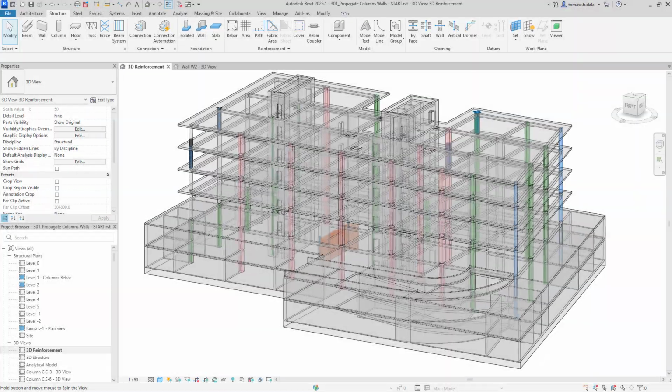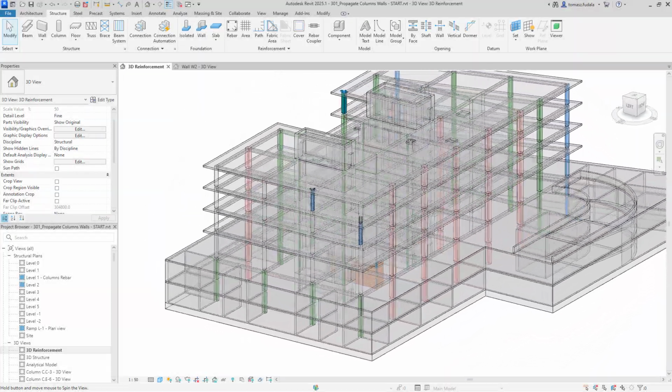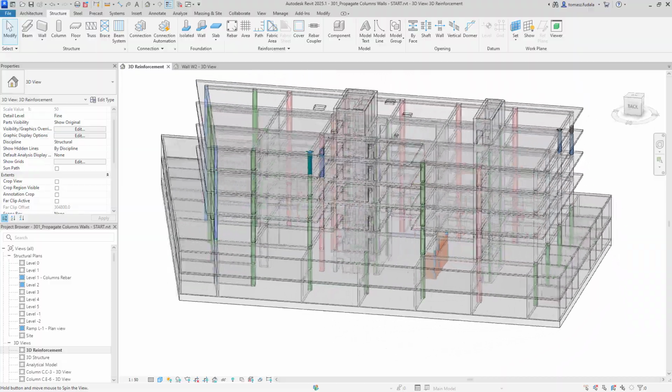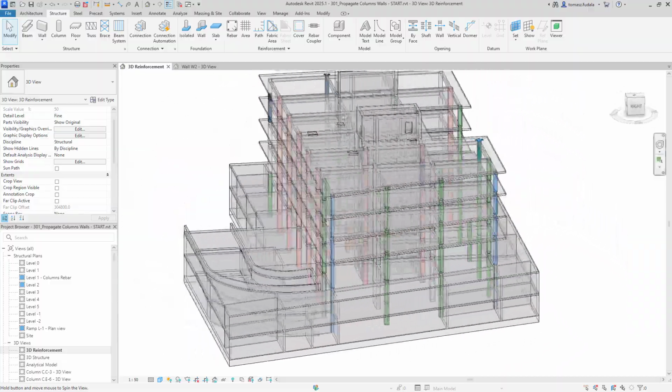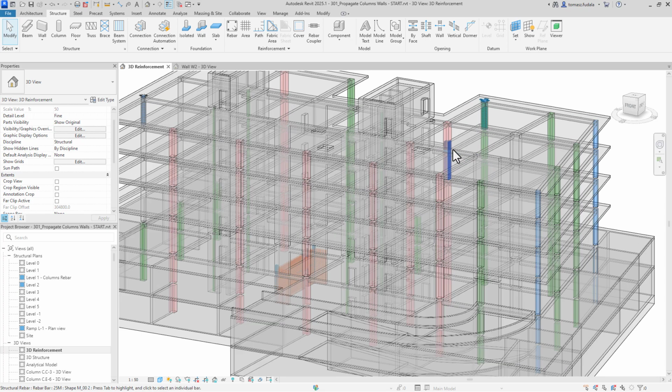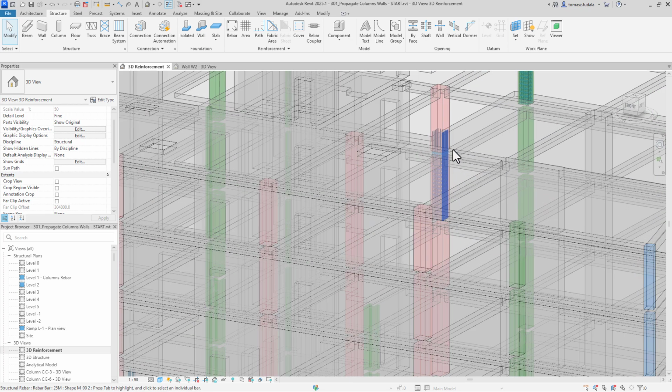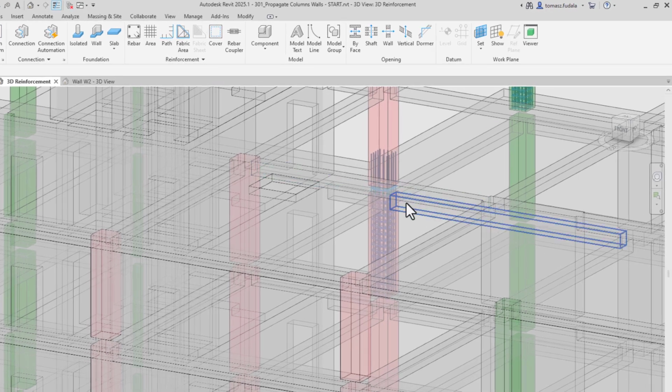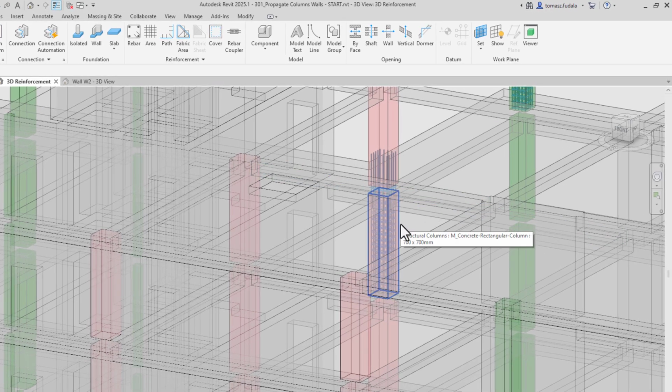In this episode of the Concrete Detailing in Revit series, you will discover how the rebar adaptive propagation feature can enhance your productivity while detailing concrete structures in Revit. When you are working on a design that has similar concrete elements, you can quickly and accurately copy shape-driven and freeform rebar from one concrete host to another.